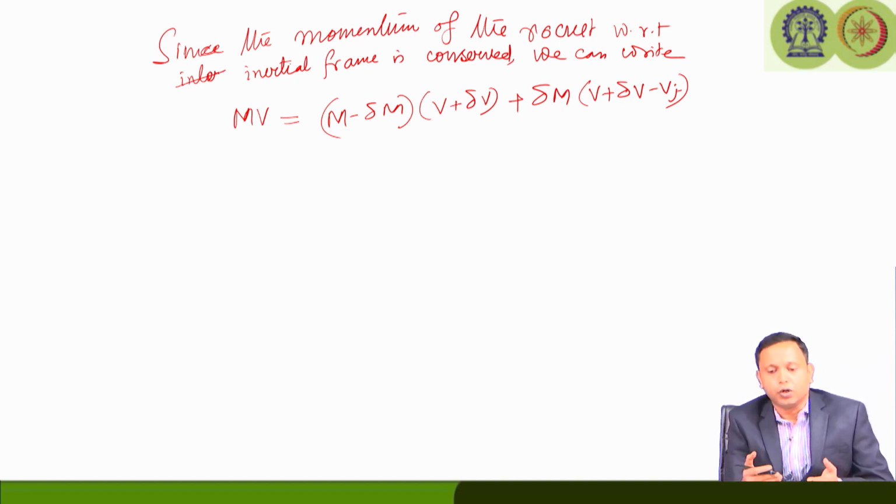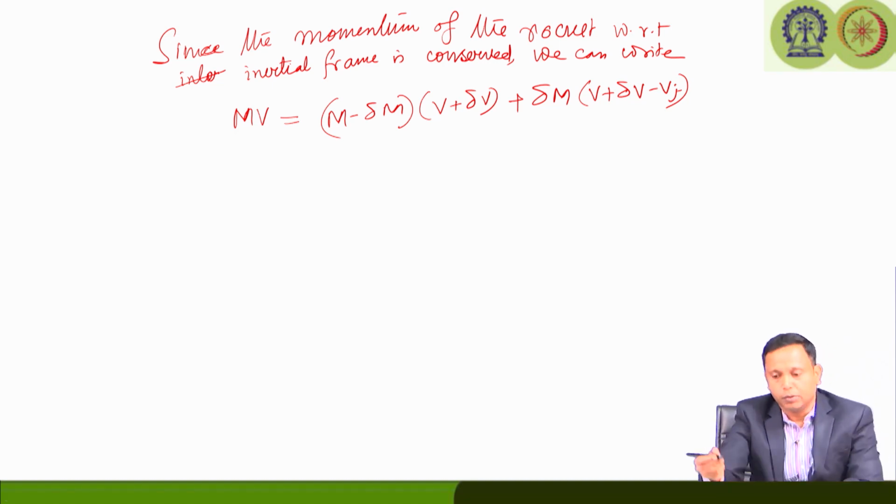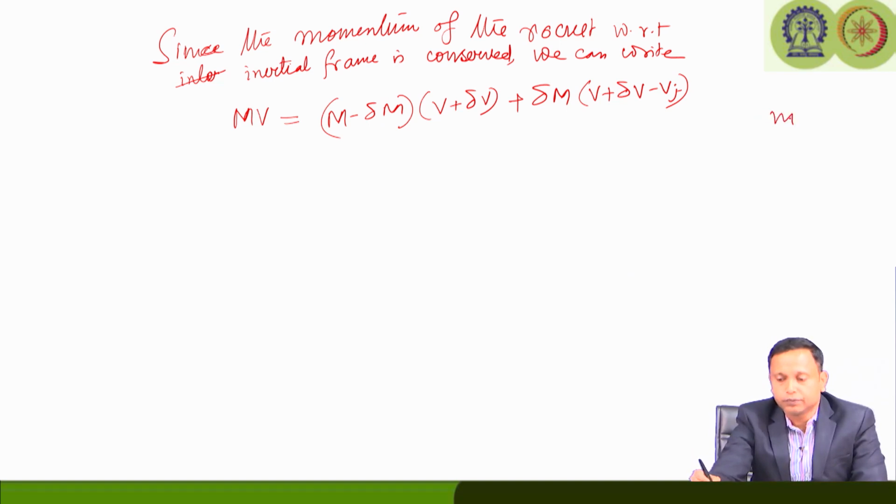the thrust. So, in principle they are ejecting their stored mass, meaning the mass which was already there in the vehicle is coming out. So, the principle of a rocket is nothing but ejecting out its stored mass to generate thrust. If you look at it, the ejected mass is delta m. If we consider the mass ejection rate as m dot, we can write this delta m in terms of m dot as m dot into delta tau.